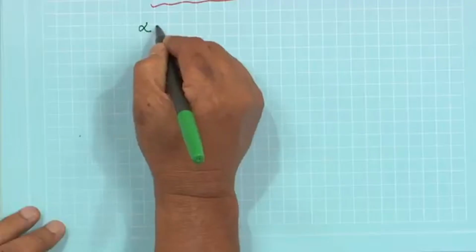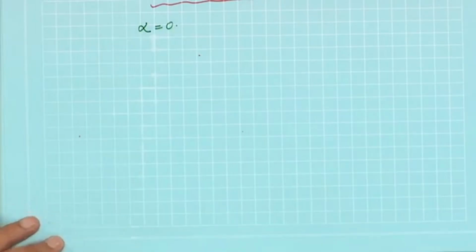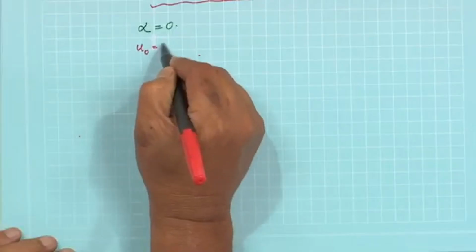So, welcome to this lecture. Today we will see the broadside array. Now, what is a broadside array? When the progressive phase shift we make 0, that is the broadside array. So, that means no progressive phase shift between elements. So, all elements are fed in phase. So, the moment we do this, we are getting u0 is equal to 0.